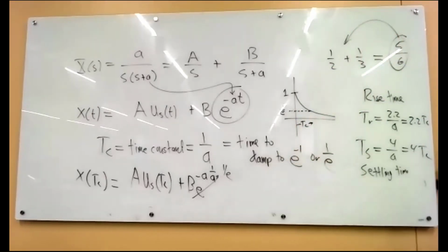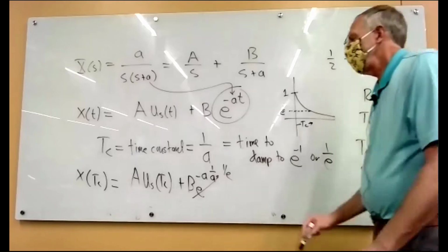So if you have a system, an airplane or a banana manufacturing machine, I don't know what that would be, and you say, okay, the rise time of my machine is 3 seconds, people can compare it to their machine and their rise time, and that just tells you how the system behaves. Or you specify your settling time, or you specify the time constant.